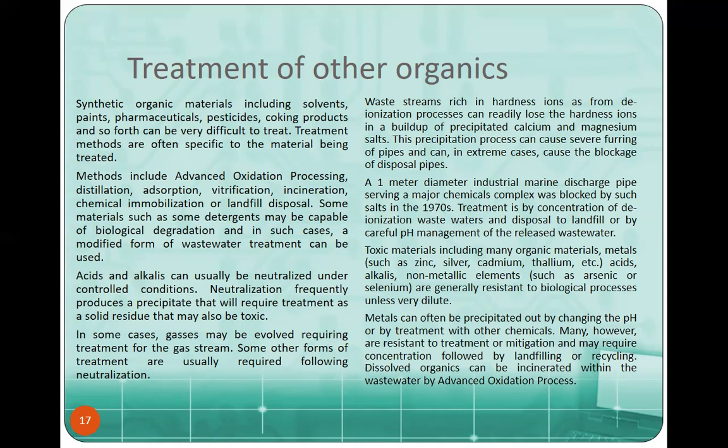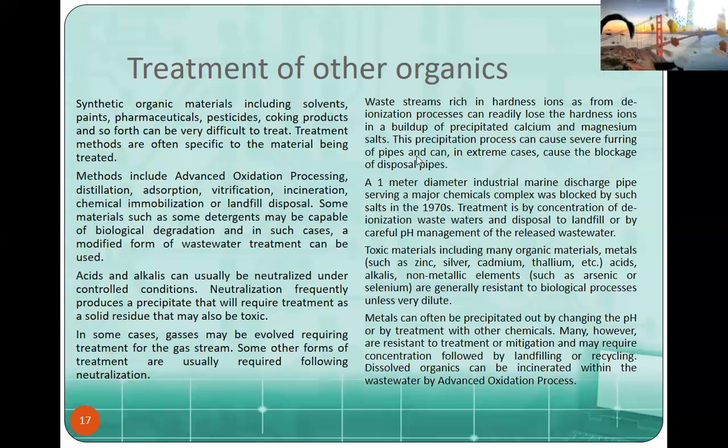Acids and alkalis can usually be neutralized under controlled conditions. Neutralization frequently produces a precipitate that will require treatment as a solid residue that may also be toxic. In some cases, gases may be evolved requiring treatment for the gas stream. Some other forms of treatment are usually required following neutralization. Waste streams